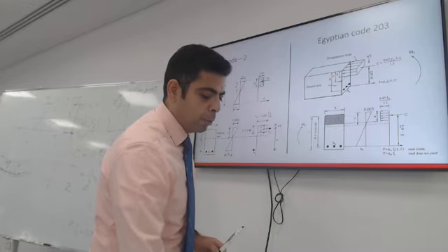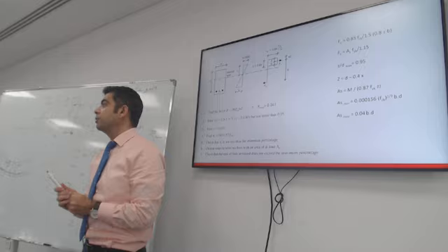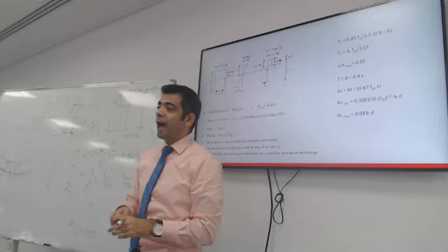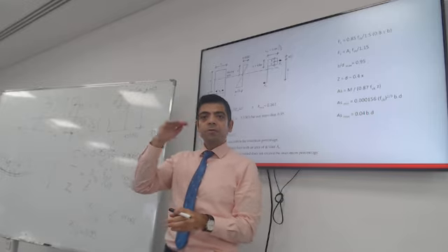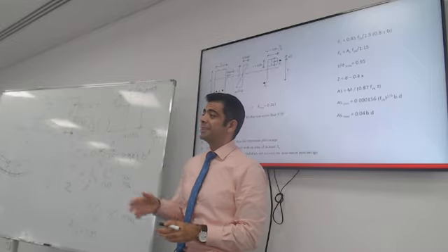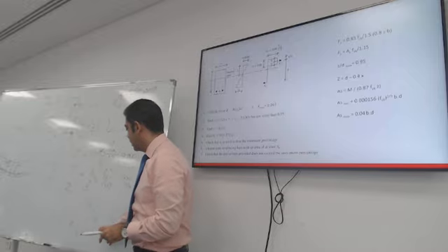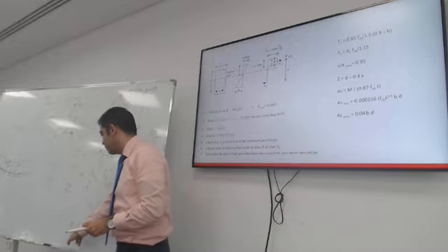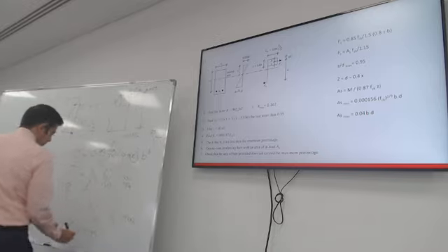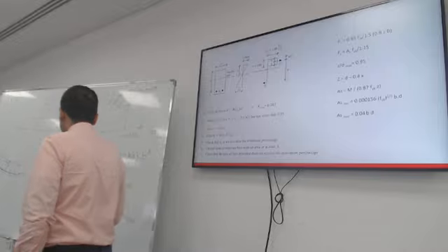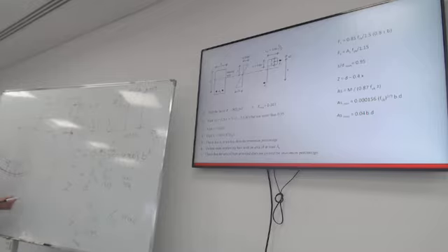It will probably make much more sense when we do the numbers. We'll do that in the tutorial. I just want to give you a quick summary of how to find these numbers step by step. Do you have a question? What's the max? Let's control Z over D to be maximum. No, I mean in X over D. In X over D, there is a relationship between Z and X. Z equals D minus 0.4x.